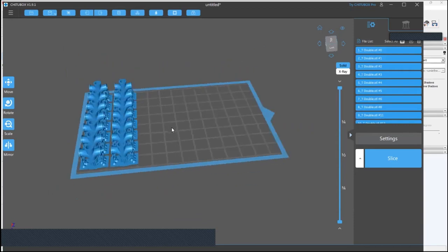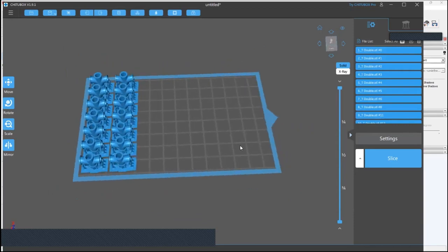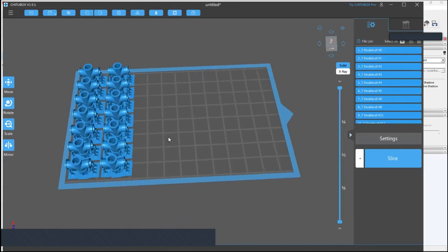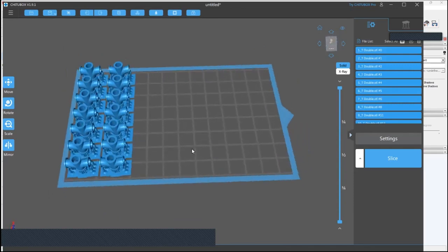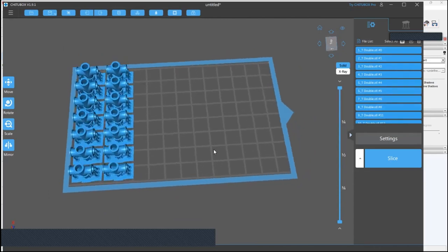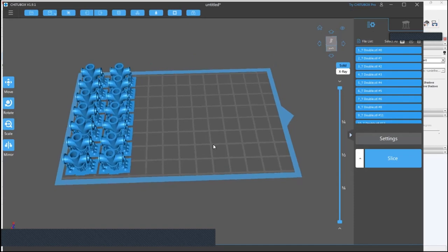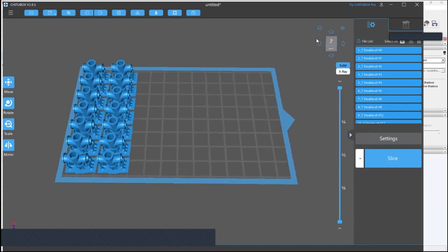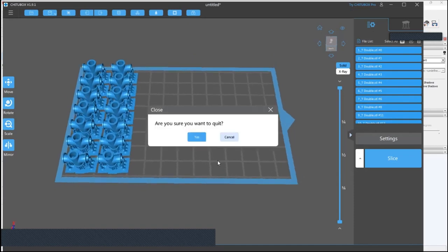Put your next slot in, fill your bed up, always fill your bed up with resin print, even if you chuck the sacks on or something, because it takes the same amount of time to print one of these as it does a whole bed. So it's not like FDM. So, yeah, that's my little spill.